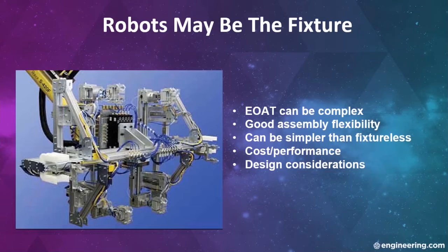Now, either way, this vision of the future, it'll combine the traditional role of the tooling engineer with the robot motion coder. The basic principles are going to be the same, but for the fixture as the end-of-arm tool, weight and inertial mass are major factors in repeatability and cycle time. So the need for rigidity with minimal weight means that traditional engineering methods for fixturing large assemblies involving things like conventional mild steel are going to have to be replaced with light alloys, composites, or maybe even highly skeletonized, additively manufactured components. I'll talk about more of the additive manufacturing aspect in a minute.